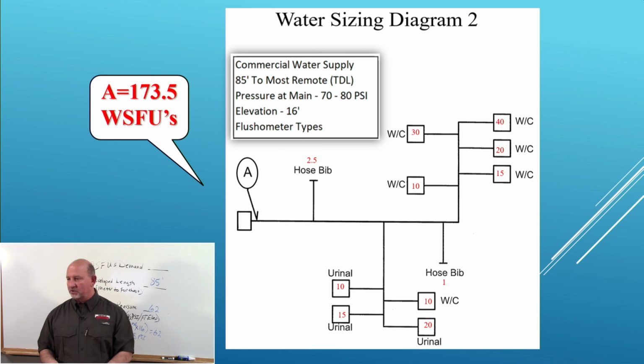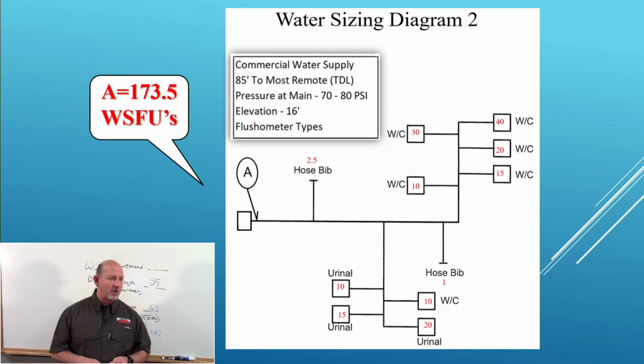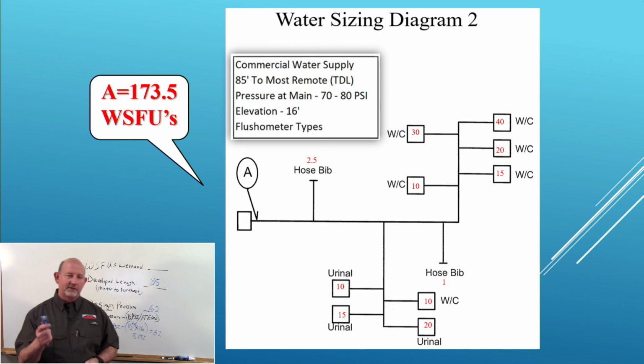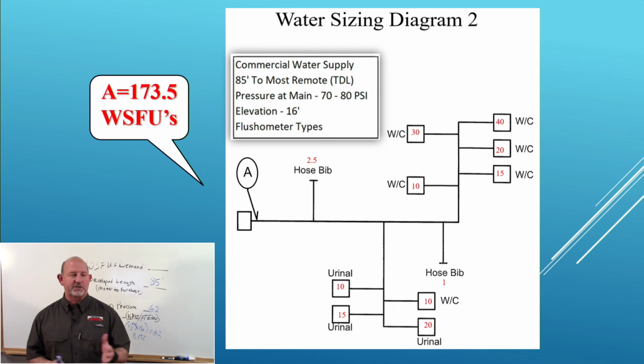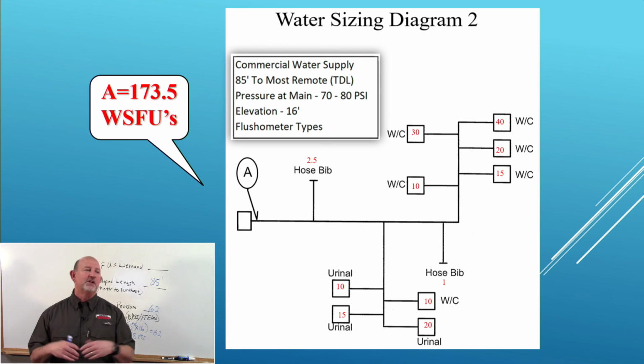And then we have one additional down on the bottom, not because it's on a different branch, we just have 6. So here's what that note says: plus 10 for each additional fixture in excess of 5. That one flushometer valve water closet there would be worth 10 more. Again, if I were doing this, I would have just said 6 water closets equals 125, been done. 3 urinals equals 45 and been done. So again, this is a little bit more technical than it needs to be. 6 water closets worth 125. 3 urinals are worth 45, done.